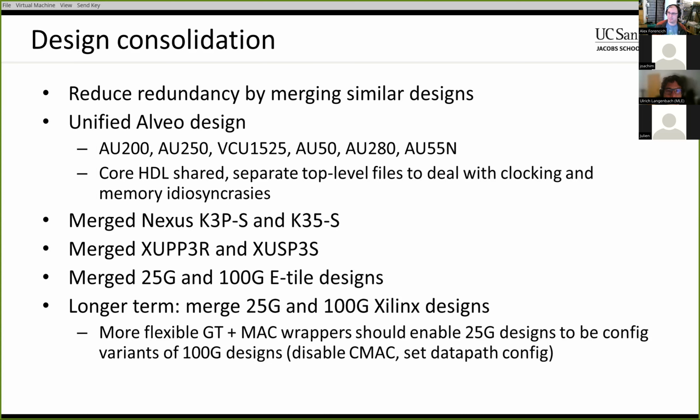So once I made that realization, I'm like, well, hey, I can just merge all of the Alveo boards into a single design, basically, that has a single FPGA core file, and then we can have, I think right now it's like 4 different top level files. So one of them is for the U200, U250, 1525, and I got one of them for the U50, one for the U280, and one for the U55N and C. And then I guess I put one together as well for the SN1000, but that's not in the repo yet. More details on that in a bit. But yeah, the idea here is this will share that core file, that core logic across all of these boards to make maintenance a little bit simpler.